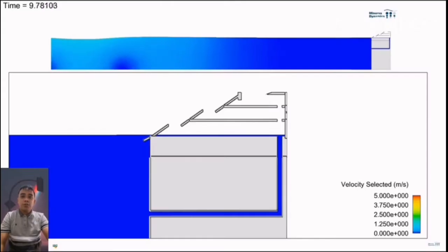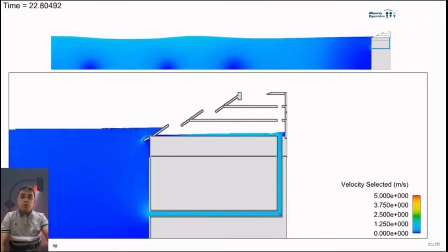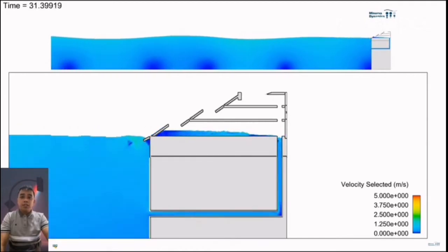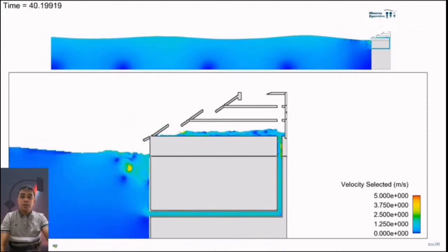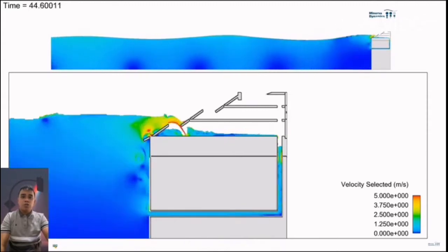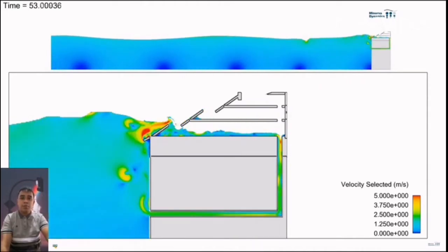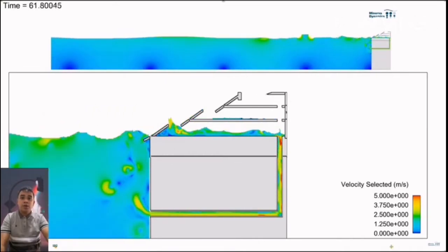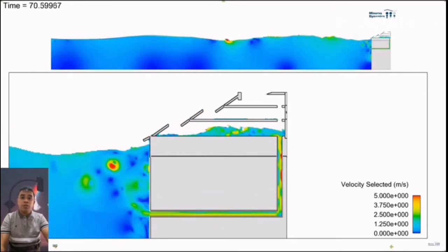This one is an overtopping converter. It allows waves to deliver water over the top of the structure that captures it higher than the sea level, and then releases the water to drive a hydroelectric turbine, similar to a hydroelectric dam. Ocean swells that would normally crash on the shore or cliff are instead directed up a ramp to a water tank approximately 3 to 5 meters above sea level. The water is then released through a turbine back to sea level.